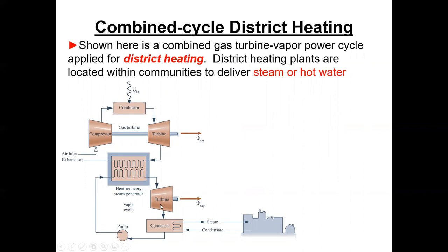Maybe we come out of here at 100 pounds, which is what, 327, I think. 100 PSIA is like 327. So that would be like 85 PSIG, which would get you 325 to 330. That's plenty hot enough to heat your home. You could probably come down to maybe 50 PSIG or whatever and still have enough temperature to make this useful for space heating.